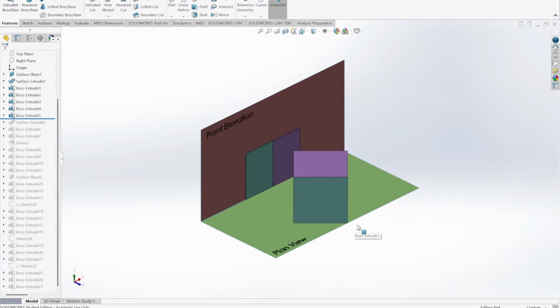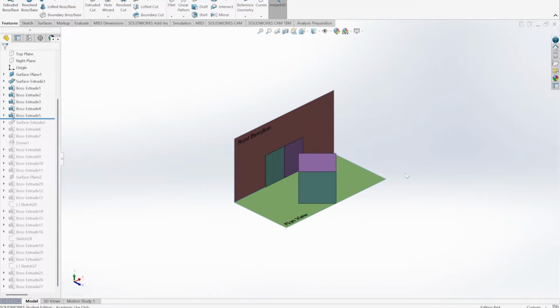What we're going to do then is find what's called our picture plane. The picture plane is essentially a surface that sits right in front of our object, and you can see we've got our picture plane labelled. It is the plane on which we are going to draw the full perspective question. In order to draw it, we need what's called our spectator. The spectator is essentially the person or something that is looking at the object at a particular angle, and we will use the spectator as reference when we're drawing our perspective drawing.